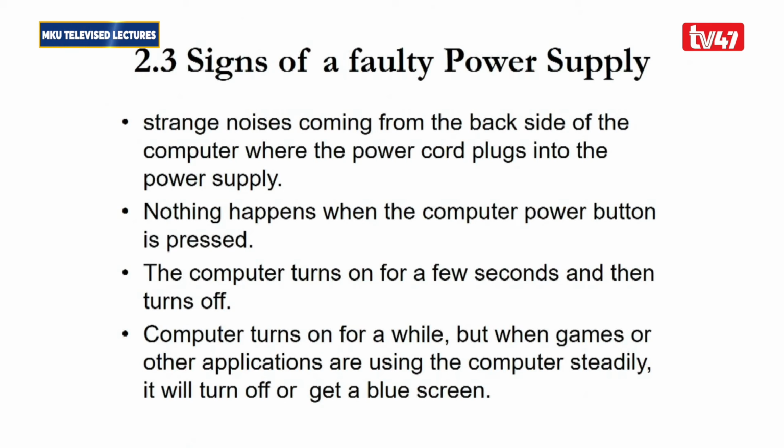And again, in case you connect the computer and nothing happens, this could be a sign that power is not getting through to the power supply unit, or maybe the power supply unit is not producing different power voltages to different components. Therefore, you need to test this with the use of a multimeter to check that power is getting through to the computer. Sometimes again, the computer may turn on for a few seconds and then turn off again, or it may keep on restarting each and every time. It could be an issue that there is a problem in the power supply unit. Therefore, it is important you test the voltage by use of a multimeter.